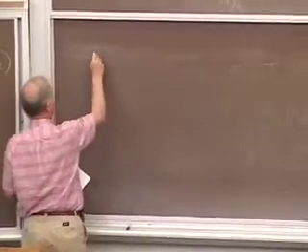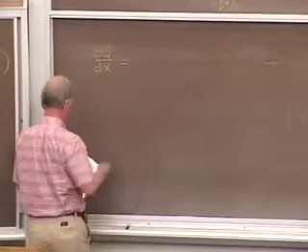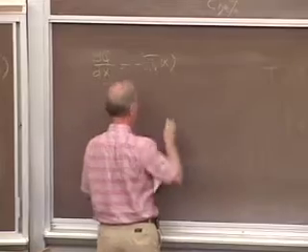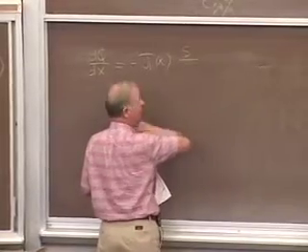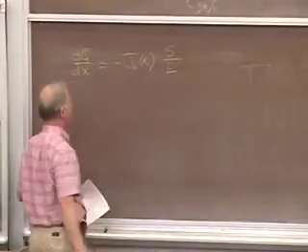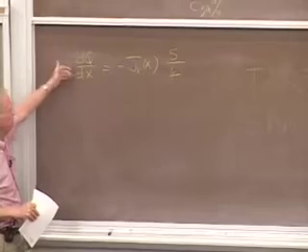And to do that, you just simply say, well, the rate of change of flow rate along this capillary is equal to minus JV of x, how much fluid leaves it, times the area. So this is now a flow rate divided by the length of the capillary. That's surface area per length. You'll see that these units agree.